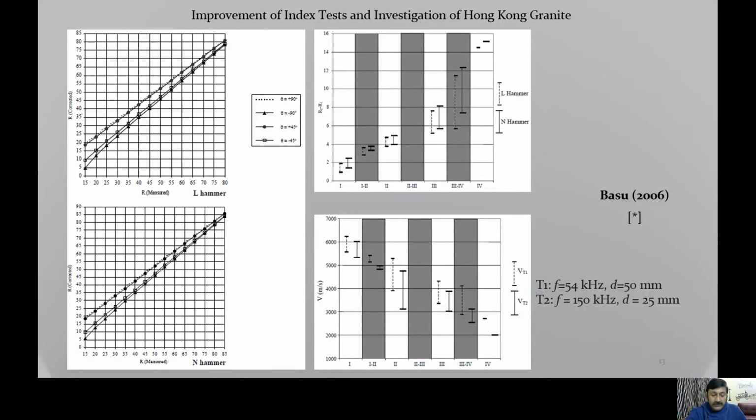So when we say beam characteristics, it is the sensitivity of the beam, the beam spread angle, and also the near field length. All these beam characteristics are influenced by the frequency and diameter of the used transducers. So if we have different sets of transducers, which transducer pair should we be using?